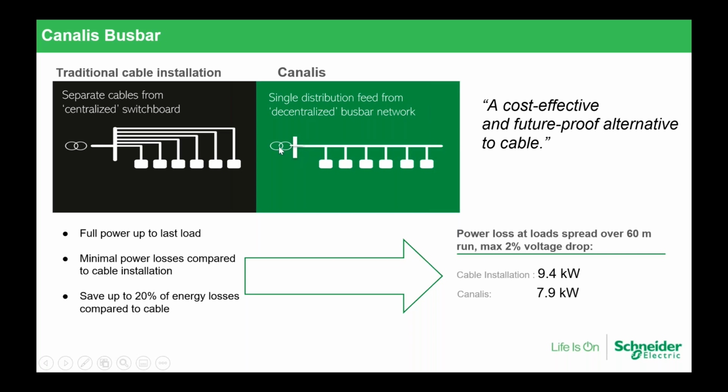You go with the Busbar from the transformer to the main switchboard, and from the main switchboard we go again with, for instance, a 1600 amp switchboard. You go with the Busbar 1600 amps, you transport full rating, and from this Busbar you supply the distribution boards with the tap-offs. Here every distribution board has a tap-off, so you see the amount of cables you are using and the decentralized distribution you are having.